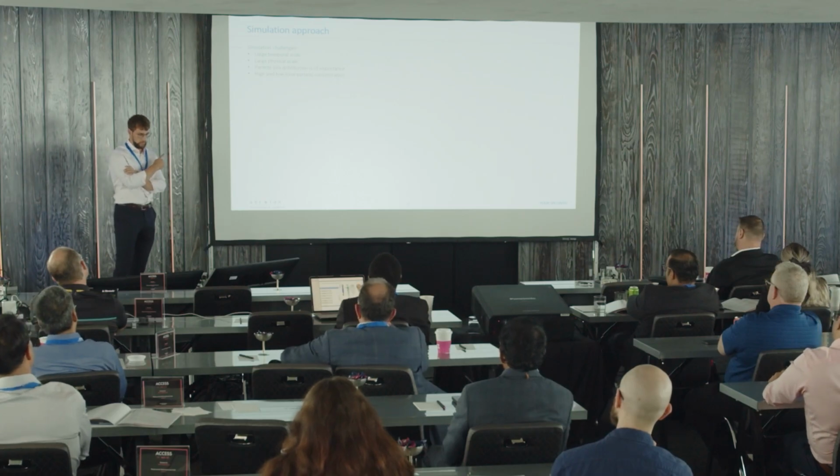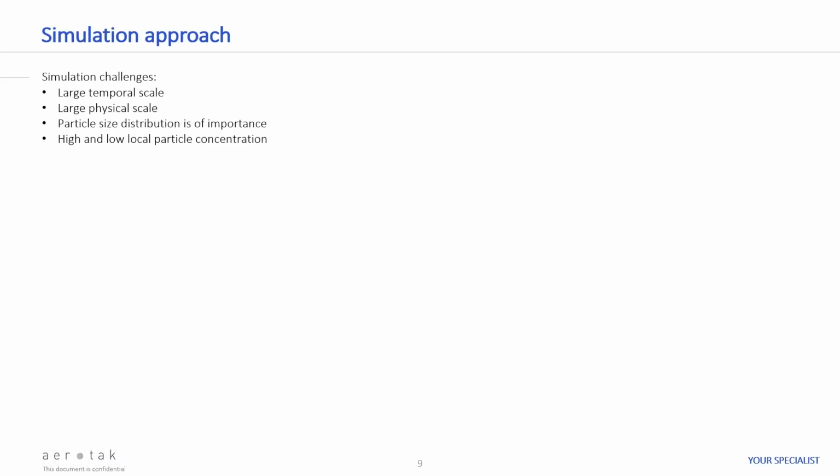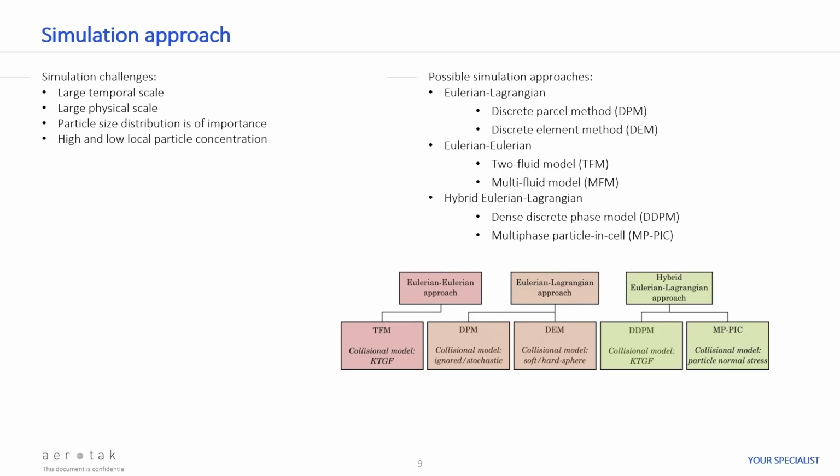The second thing is that filling of this hole doesn't take a minute, it doesn't take 2 minutes, it takes hours. So we also need to be able to simulate that entire process. So we have quite large temporal scales as well. To make matters worse, we also need the particle size distribution. And that, of course, is a big issue when we're talking about different ways of simulating granular fluid systems. And we have an issue that in some places of the system, we're going to have low particle concentration, and in other parts of the system, we're going to have completely closed pack. That also makes things a bit more difficult.